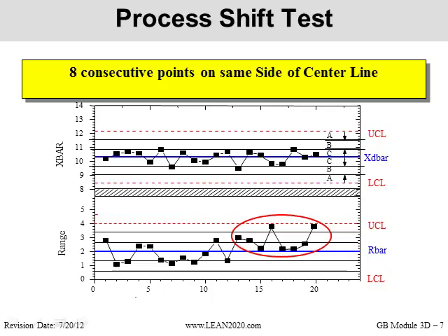I'm going to go back into my process and see, is there something wrong with my machinery or my process that's creating this out of control condition. We want to do this before we start creating defects for our particular customer. So hopefully, even though in this particular case I'm not outside my control limits, I would expect over time that I would be violating my control limits. But right now I can definitely say that I've got an out of control condition here, and this is a sign of a special cause. Something's creating this, not normal to my process.